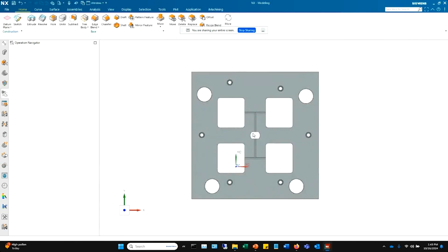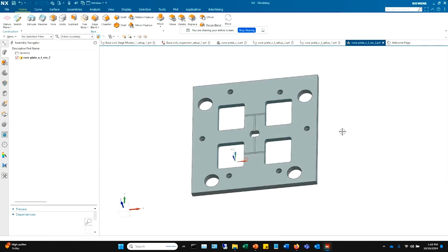The reason why no software can do a replacement is because when you Parasolid out a file or you STEP out a file, you just think of it as an enormous Excel sheet with letters and columns. All of the data of this file is just dispersed through letters and columns. When you bring it back into a software, it has an encryption key that's Parasolid or STEP that tells it where to go back to. If you were to do a revision of a part and export a Parasolid, there's no guarantee that it's going to go back in the same places. So there's no associativity between it. With our software, everything remains 100% identical.